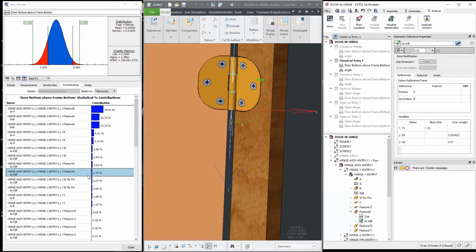And now notice, I didn't change the tolerance, just changed the material modifier. And so we'd have to obviously go look at the size to see how much bonus we were getting. But notice that now we're at 8 or more down. So that one little M made the difference between 2% contribution from this feature or 23% contribution from this feature.